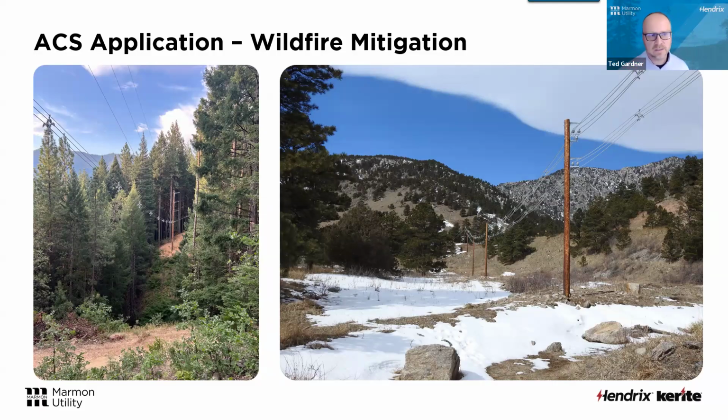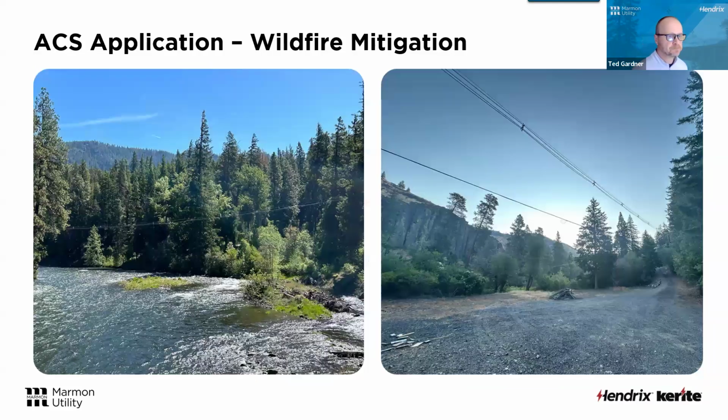the air. A lot of people are kind of focused on cover conductor for wildfire mitigation. They don't want it to spark when it hits the ground. Our goal when it comes to spacer cable systems is really keep it up in the air longer. You want to minimize damage to the line, damage to the poles or the brackets or anything like that. And if we keep it up in the air longer, there's little to no opportunity to ignite.